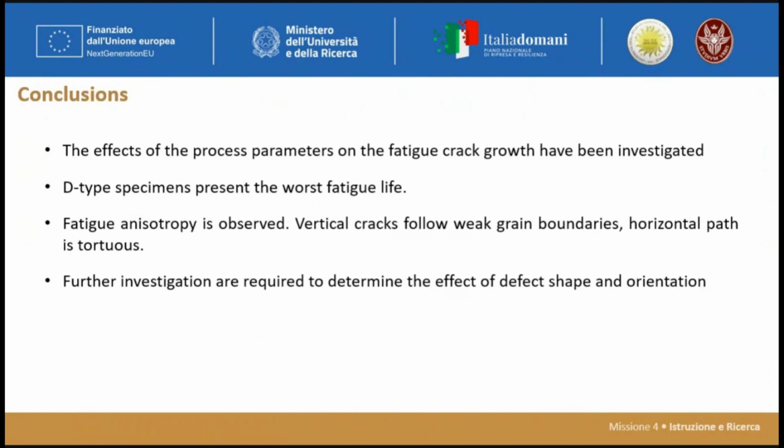So, in conclusion, I have analyzed the effect of the process parameters on the fatigue crack growth rate. The specimen printed with low energy presented more defects and consequently low resistance. We observed, especially for this specimen, a sort of anisotropy.